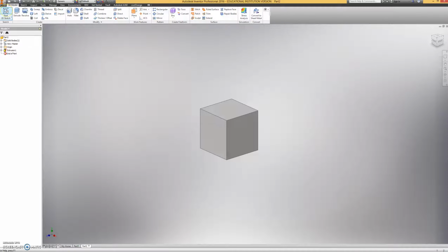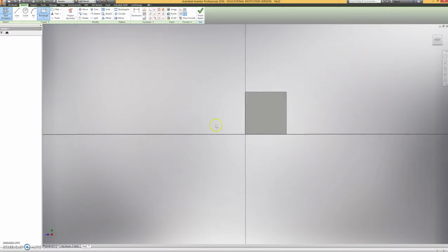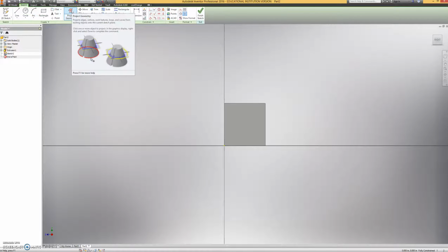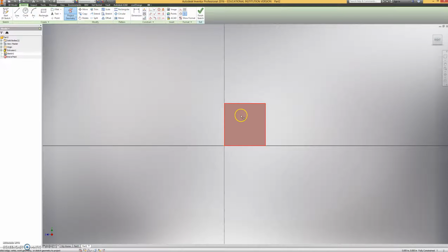To build off of that, I can create additional sketches. I can click on any surface really. I'm going to go for the one on the right. And I could take the rectangle tool, click in the upper corner there and trace it out, but there's also this feature called Project Geometry, which is very helpful. So I'll show you how to use that. It's simple: turn it on to click it, click on that surface, and now it's traced the outside profile.